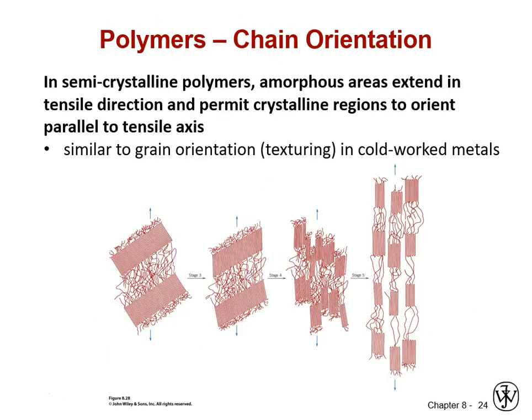Polymers, okay? What happens if you don't have to move dislocations to move material? Polymers have those continuous, amorphous regions between crystals. In some cases, polymers are totally amorphous. So the whole concept of dislocation movement and strain field interaction and everything is now either out the window in the case of an amorphous polymer, or all of that is happening at the same time and in parallel with chain alignment and reorientation via these amorphous regions.